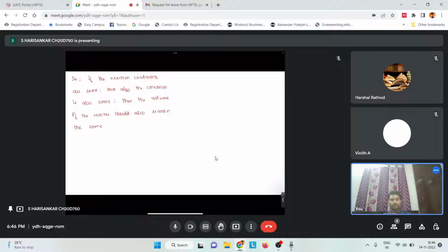Okay, so using this, we'll try to see how we can proceed. First, what we need to find here is the volume of the reactor, the volume of our plug flow reactor. It is given in the question that this plug flow reactor is made of 7 stainless steel pipes of 6000 millimeter length. So the volume of this PFR will be 7 into the volume of a 6000 mm long pipe.